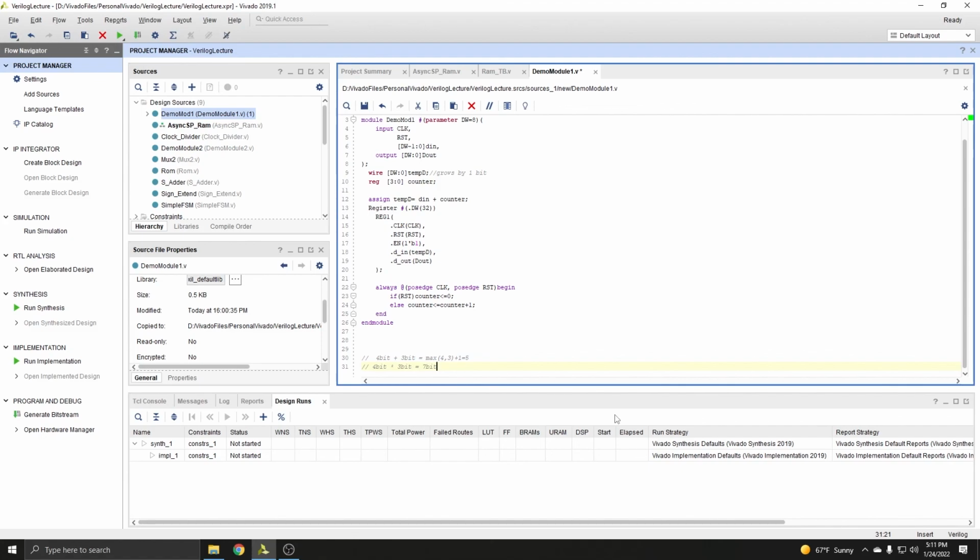So you write your module, let's say, because I know in the single cycle, which I believe you should be starting somewhat sooner rather than later, you have to have a register, an instruction memory, a data memory, a register file, some multiplexers, an arithmetic logic unit, a control unit, some adders, some various modules.